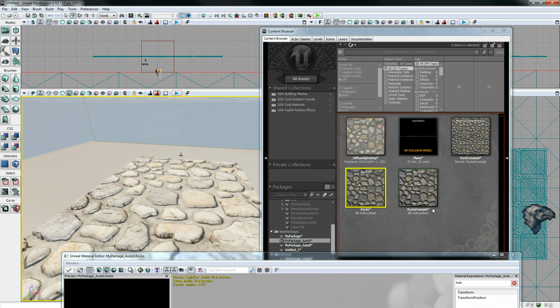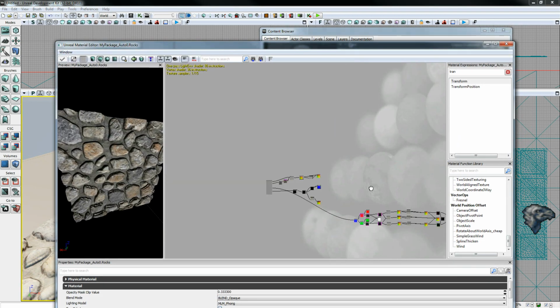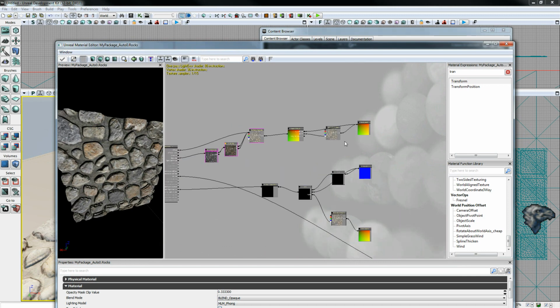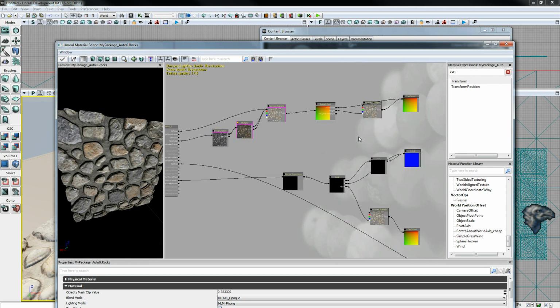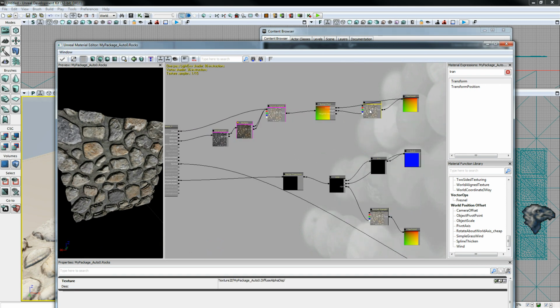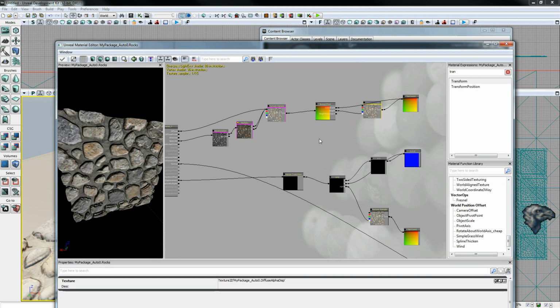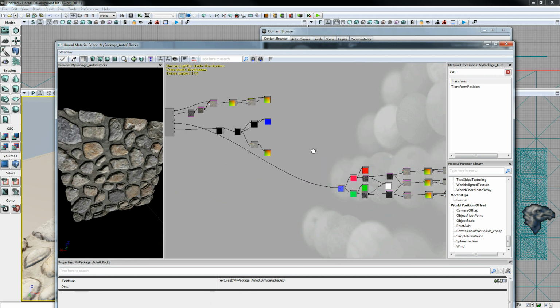So now I'm going to set it up for using a material constant. So everything I've got now is a standard, it's just one texture. I can't use it anywhere else. So what I want to do, if I were going to use this for a constant, is change all my texture samples. You just right click them, and you hit convert to parameter. So what that'll do is it'll allow you to just literally plug in a different texture later.